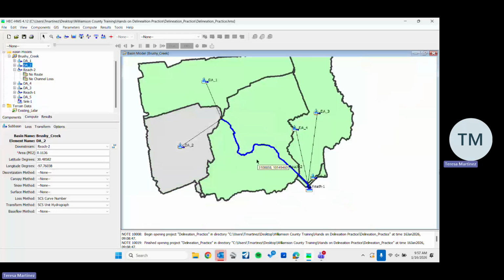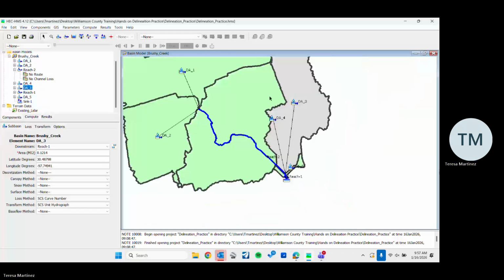And I guess essentially, if you put in an area bigger than the LiDAR file, then at that point, what the drainage areas being shown, are they just on the schematic view only, or is it actually changing our results at the outfall? If I change from 0.1 square miles to 0.5 square miles or 0.3 square miles, when I was identifying streams at that step.